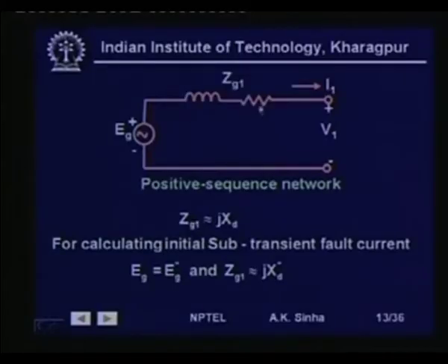and the generator has the winding resistance as well as armature reactances coming into picture. So, the total reactance offered by the generator can be seen, and that will be in steady state condition as the synchronous impedance of the generator, and that is also the positive sequence impedance of the generator.